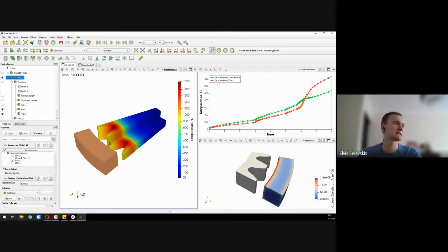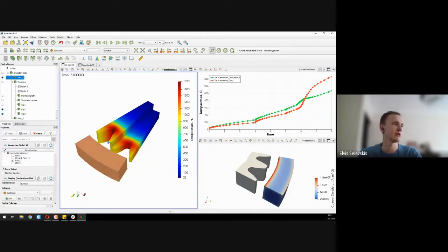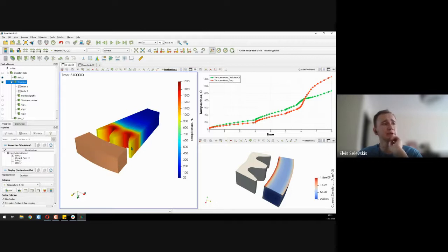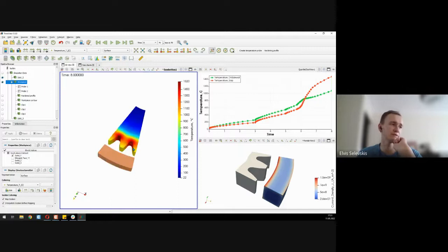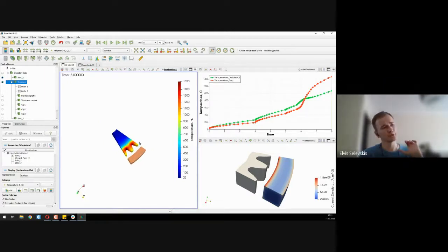Then, some of the more advanced filters, or something which I might not have touched upon yet, would in this particular case be to visualize the entire gear. Here we are working with only a slice of the gear, so 22.5 degrees of a slice. And if you would like to, we can multiply this solid multiple times, so it looks like we have a full gear here.